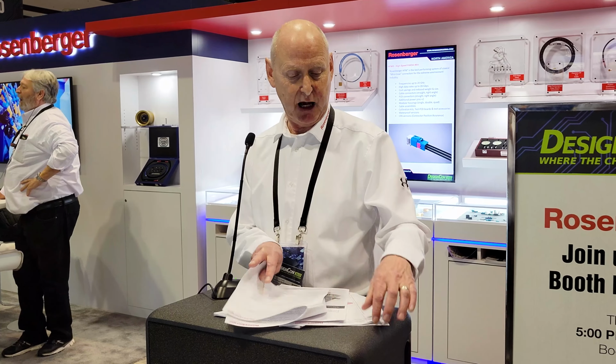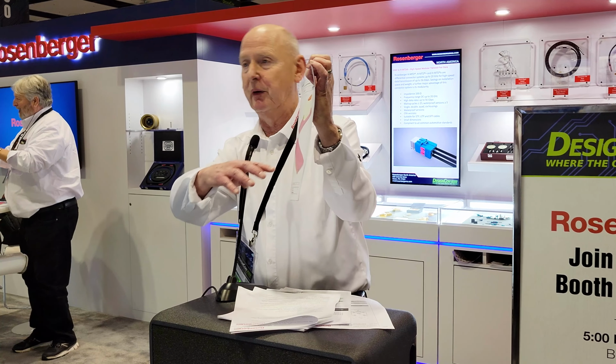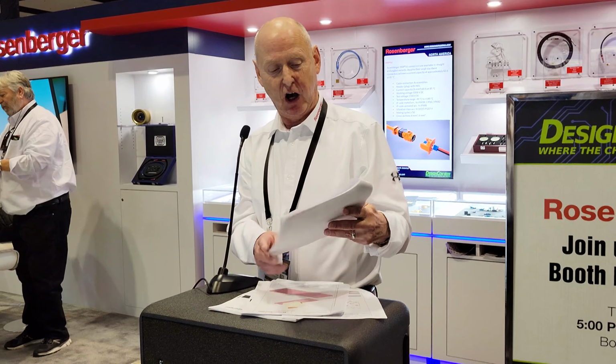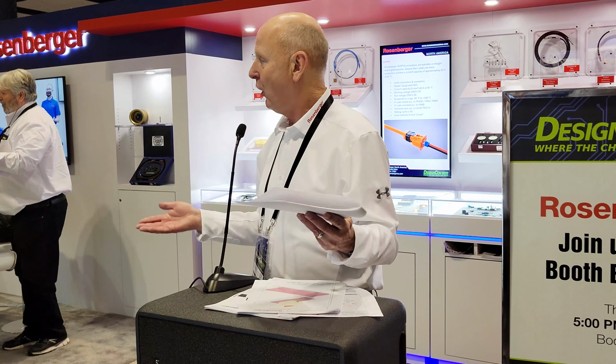Lastly, I was going to discuss some of the glossary of terms that I was talking about. At the back, at the end of this footnote, we go through those. Aperture, for one thing, and the aperture, which I was talking about, you'll see this small cutout right here. So directly under the printed circuit board's first layer is the trace, and we want to keep that open to enhance the return loss performance. There's many other things in here that I discuss: encrypted model, footprint, grounded coplanar waveguide, the whole nine yards of definitions.